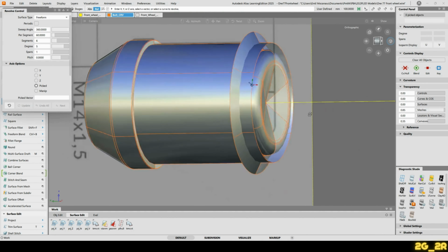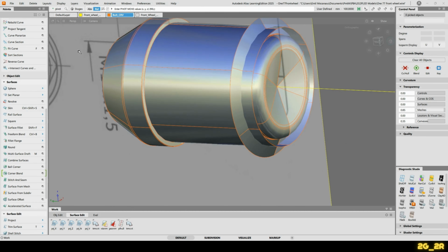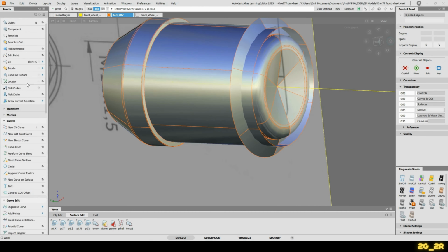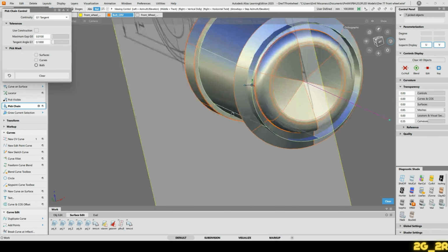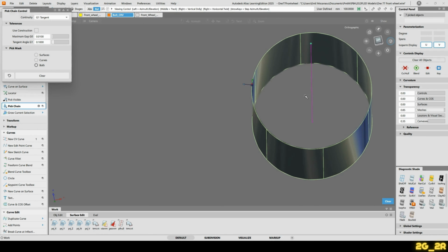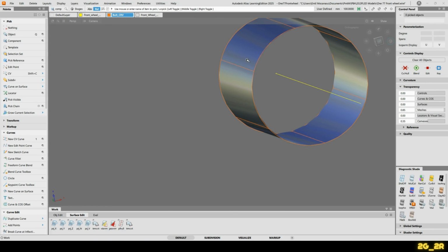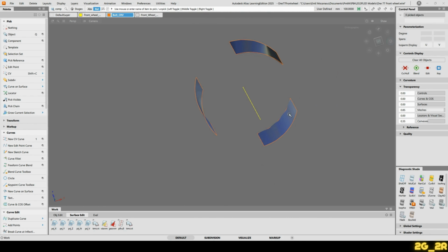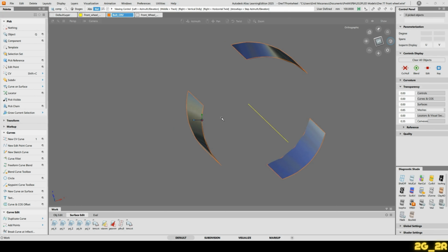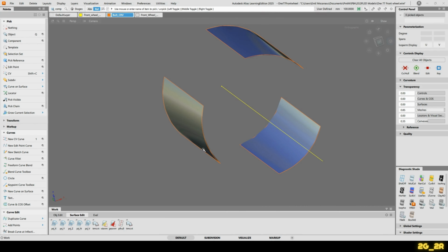And the next bit that I'll do, I want to pick these surfaces, these ones here. And that I'll do by using pick chain, and I'll use the setting tangent. Click on one of these edges, and we've got that tube there, which is amazing. Now, to make everything easier, I'll pick every second surface there, and I'll template it. And let's generate our hexagon now, and that's going to be easy by doing skins between these surfaces, these edges basically, and with no crown to that skin.